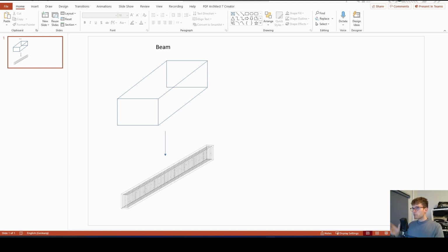Because this time it's going to be very complicated, it's going to be a lot of geometry, lines, rectangles, vectors, yeah, just transformation of geometry in Dynamo. So first we want to simplify it here in PowerPoint what we're going to do, and then later on we can understand all the nodes and how they interact with each other better. So first off, we have this beam and we want to fill this beam with those rectangulars, and those rectangulars are volumes that represent rebars.